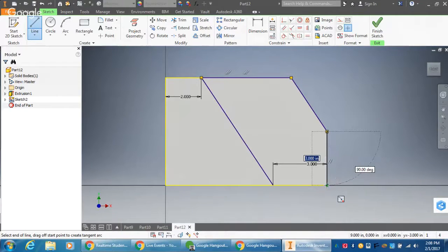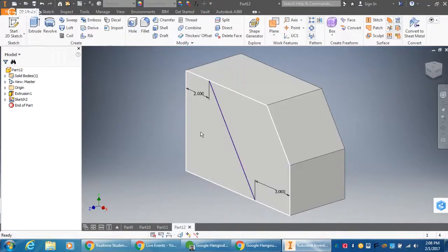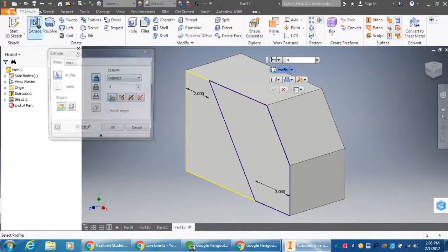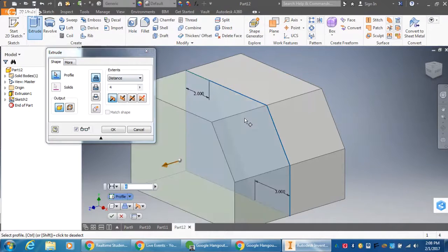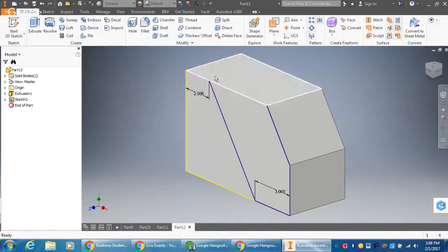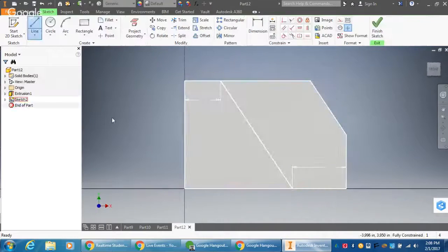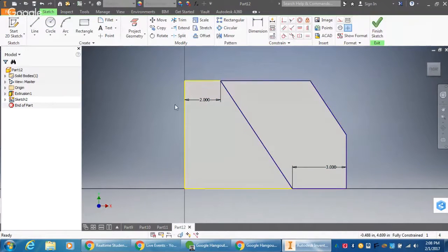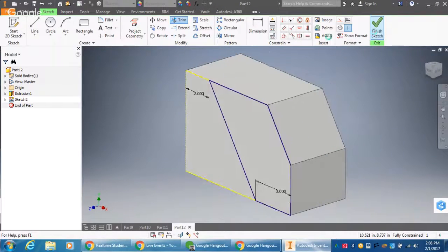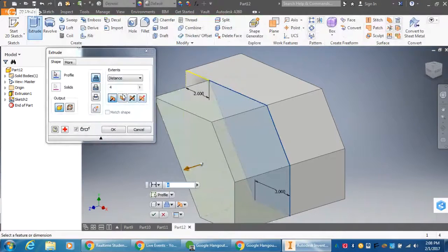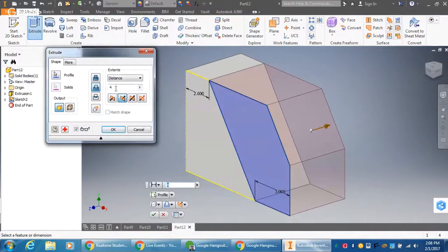Here. And what I was going to wait to show you next time is when you project geometry, because you get those errors sometimes, you actually can select all those lines and make them construction lines so the computer doesn't get confused and get very angry with you. And he's still getting angry with me. Hey, why are you always so angry with me? So I'm just going to take this line, make it a construction line. And it usually doesn't let you trim what you've projected. Nope, it's not going to. Finish my sketch. I'm going to extrude. There we go. Like I said, sometimes it's finicky.